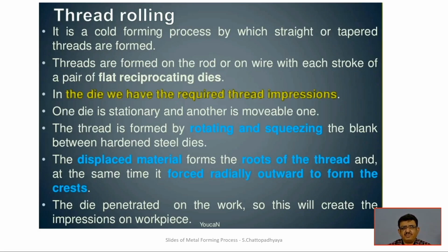Displaced material forms the roots of the thread and at the same time is forced radially outward to form the crest. So, the same material will be compressed and formed, and the die penetrates the work. So, these will create the impression on the workpiece, a permanent, long lasting impression, and that is a very productive one, because a huge amount of threads and other things can be produced within no time, and that is why thread